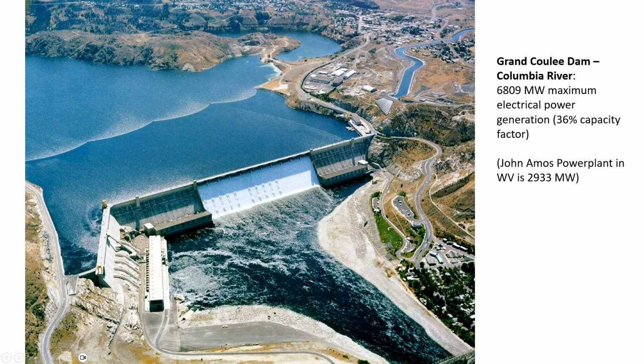Water gets through a dam in many different routes. There's typically one route that the water flows through to generate electricity, and that's separate from this overflow spillway. The spillway isn't generating any electricity because all of the energy is just being wasted as the water flows down over the front face of this surface. In order to capture the energy, you have to produce pressure, and so there's something called a penstock, a big, large diameter pipe that at one end has a turbine that's spinning around, and so we don't see those. I think that this might be where the water's flowing to generate electricity.